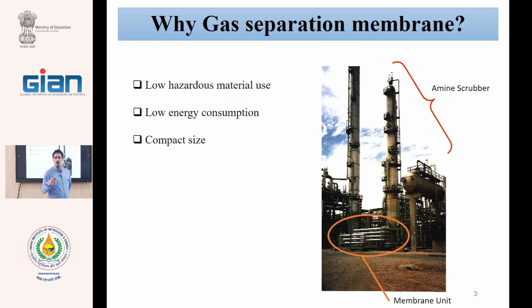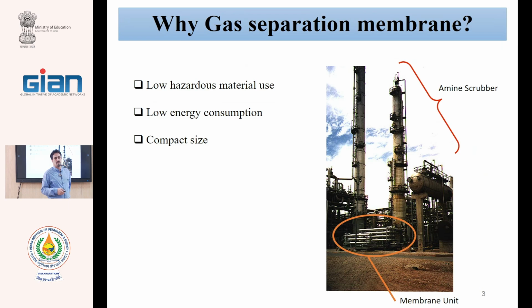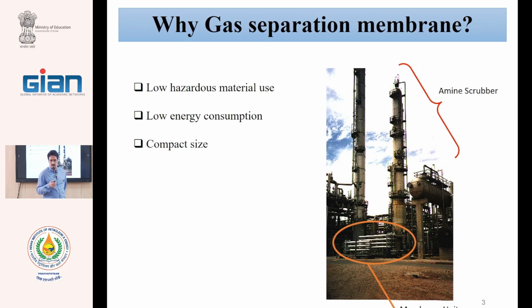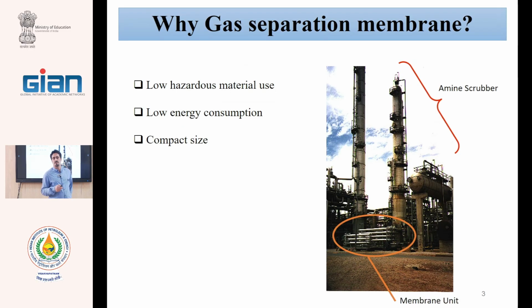Only gas comes in, and before the gas stream, we have a filter cartridge for removal of particles resulting from corrosion of the tubes. After the filter cartridge, we use a compressor. In liquid we have a pump; in gas transfer we have a compressor.